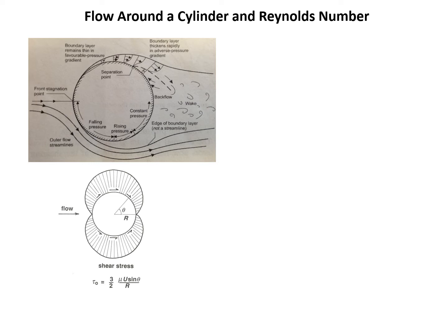Because of the shear stresses, we have this vorticity that is set up in the fluid particles. So the part of the particle that's closest to this cylinder is not moving as rapidly as the part that's farther out towards the free stream. And so you get this rotation and this deformation, this vorticity. And at some point, because of the curvature of this cylinder, in part, there's a place where the flow detaches, that boundary layer detaches, and you get a reversal in flow. You get what is sometimes also called the backflow.